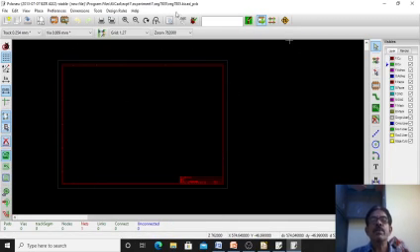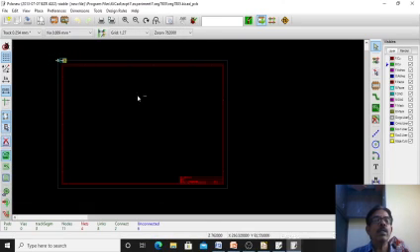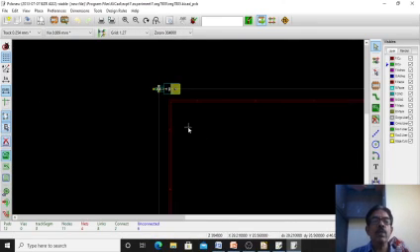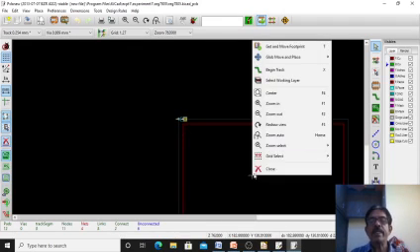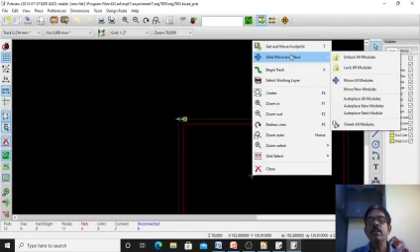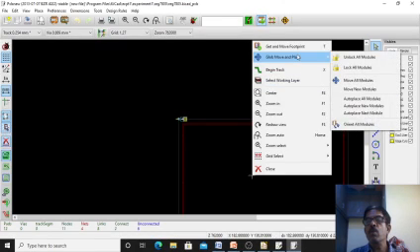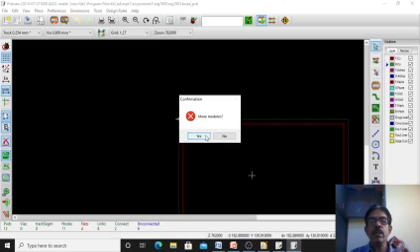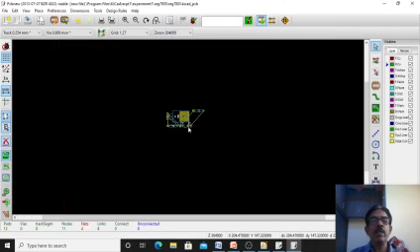Sorry, in this first you do this net, read current netlist, then close it. Okay, so now your circuit has come here, right? Now right click here, global move and place. Okay, move all modules, then you say yes. Okay, your PCB layout has come here.